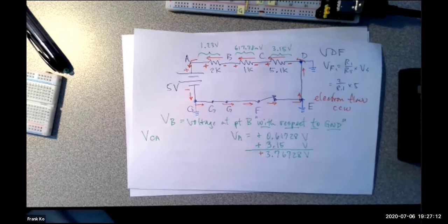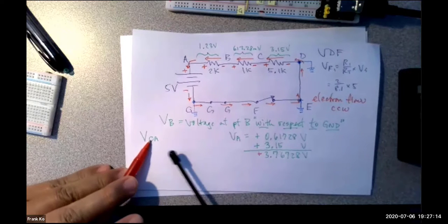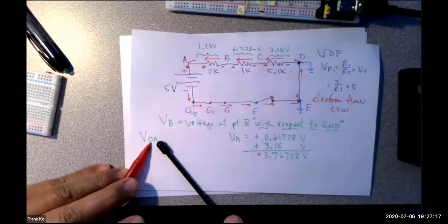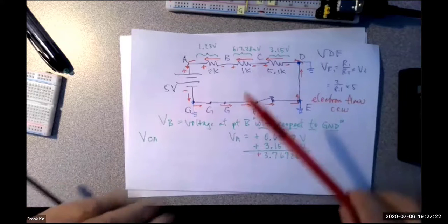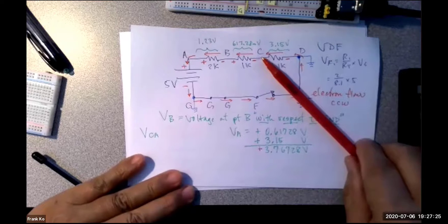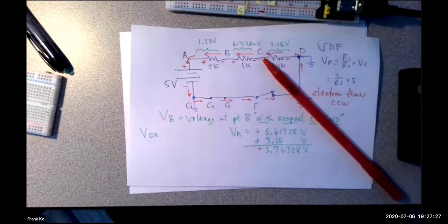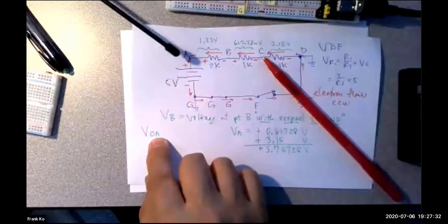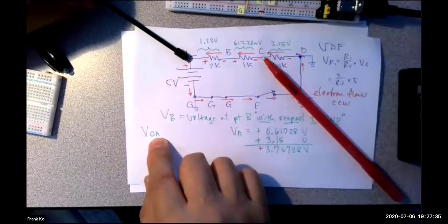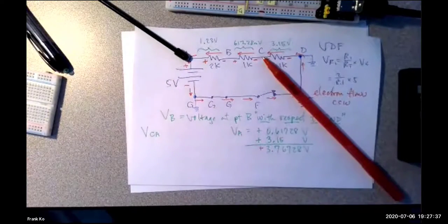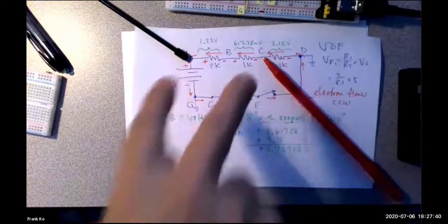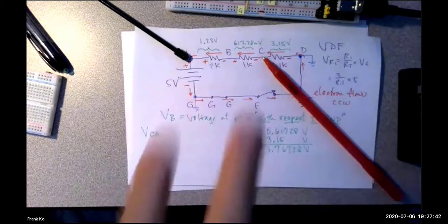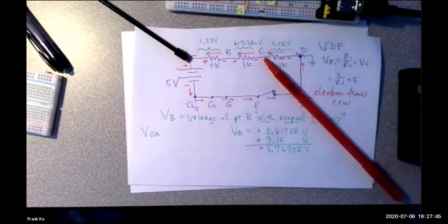All right. So we're going to put the red probe on the first. We're going to put the black probe on the second point. Are we good with that? Yes. So the red probe is going to go to point C. So I'm going to take the red probe and place it physically at point C. Is it physically at point C right now on my schematic? I'm going to take my black probe, and black probe goes to point A. So here's my black probe at point A. So now do I have a black probe at point A? Ta-da! So the question is, between these 2 points, is there voltage, yes or no? Yes. What do you see?